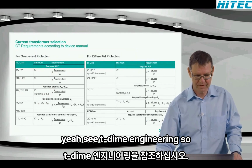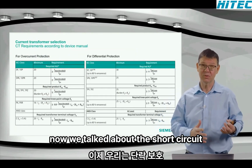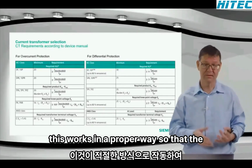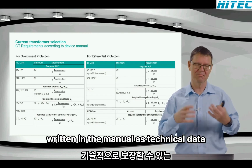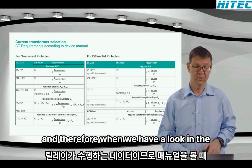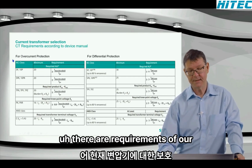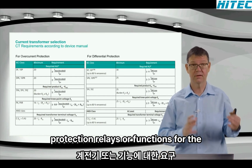CT dimensioning. So now we talked about the short circuit protection functions. The question is now, what current transformer do I need so that this works in a proper way, so that we can guarantee what is written in the manual as technical data, what the relay performs. And therefore, when we have a look in the manual, we see here an extract of the manual. We have in the appendix always the requirements of our protection relays or functions for the current transformers.